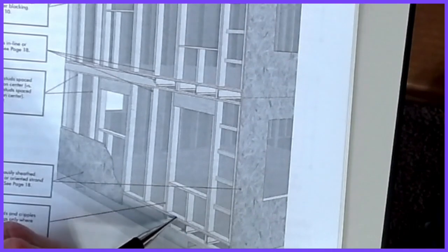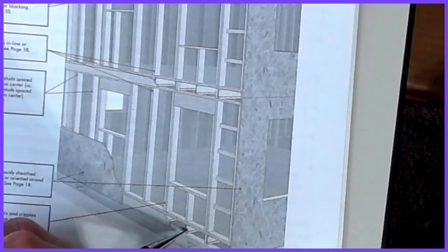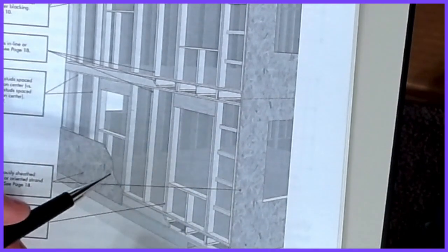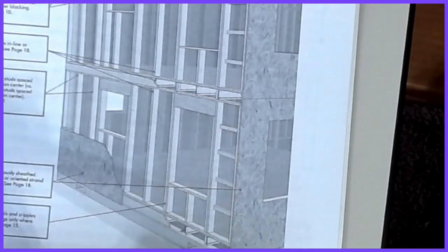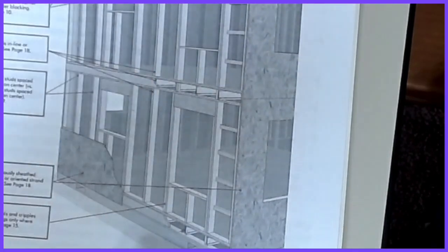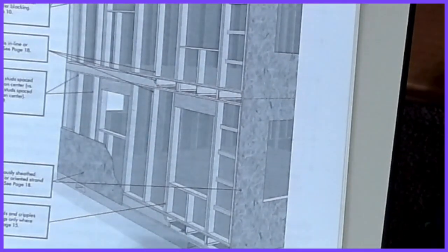This is called a sill plate. Okay, and then your floor beam is down here, and then there's another sill plate or a toe plate underneath that as well. But basically, you can prefab these walls and units, and then connect them all the way down through the beams they're sitting on into the structure that's holding up those beams. So all sorts of neat stuff.